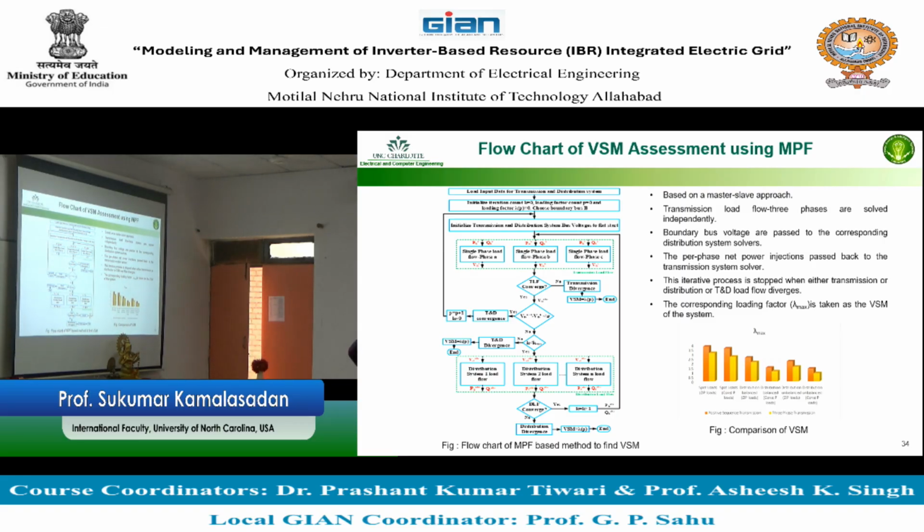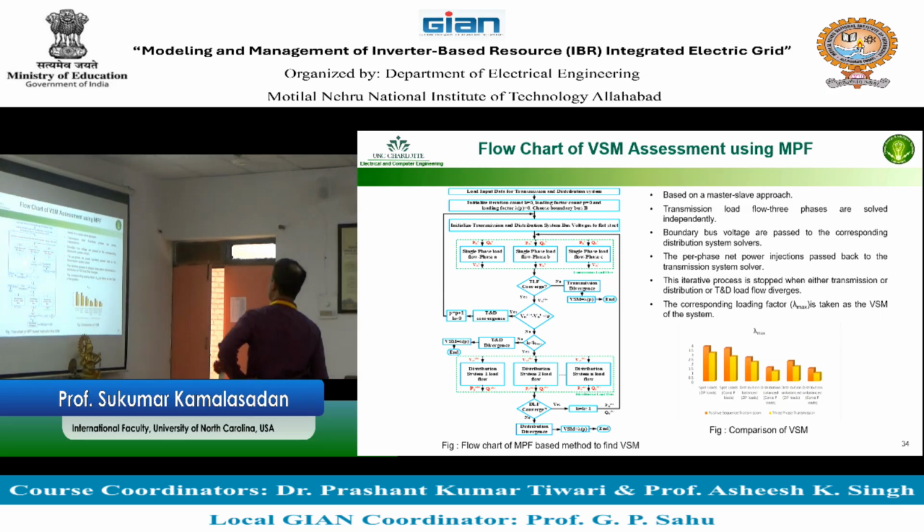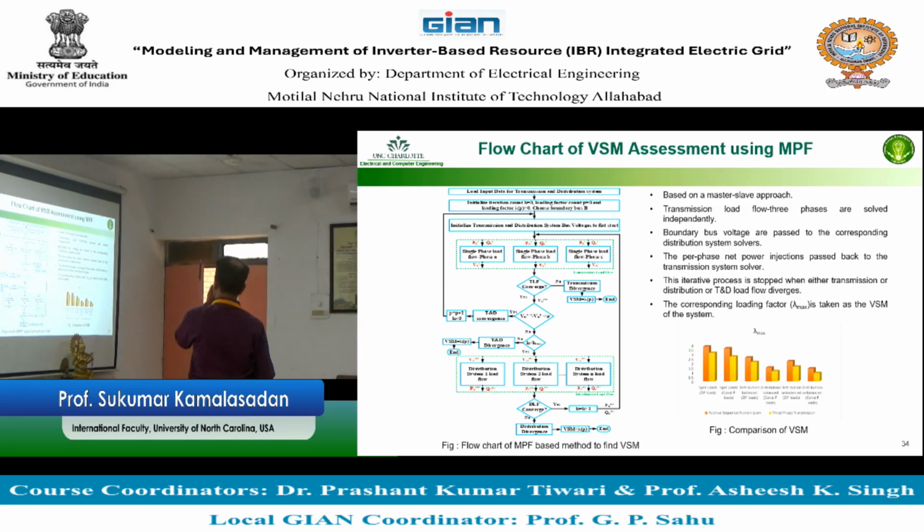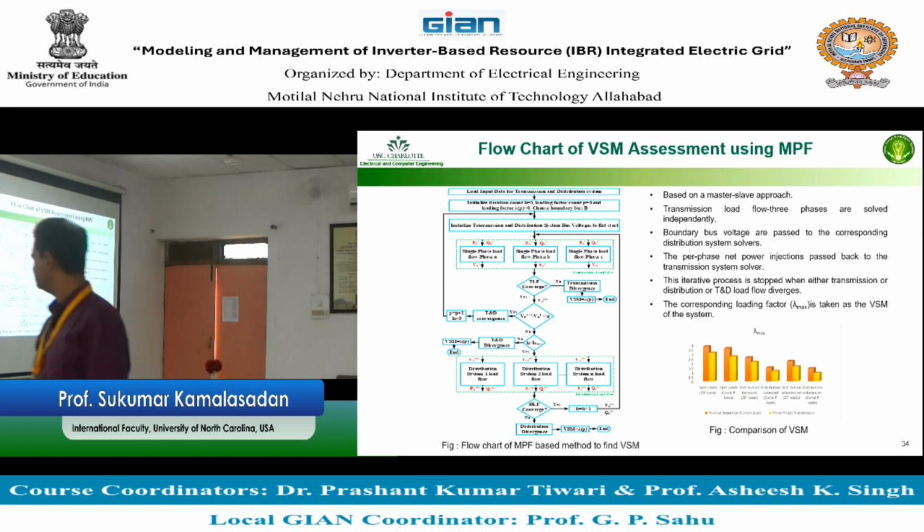You can run the time series power flow for a transmission integrated system and run the power flow for each phase till the system converges. And once the system converges, you can change the power, and then what you can plot is the voltage stability margin.